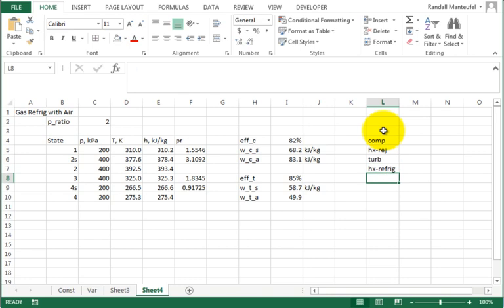All right? And then we're going to have Q in kilojoules per kilogram for each component. Is there a heat transfer per unit mass flow through it, as well as work in kilojoules per kilogram. This table you've seen before, it has 8 entities. 4 of them are 0. So let's put the zeros in. So the compressor, adiabatic, turbine, adiabatic. Both heat exchangers, no work.